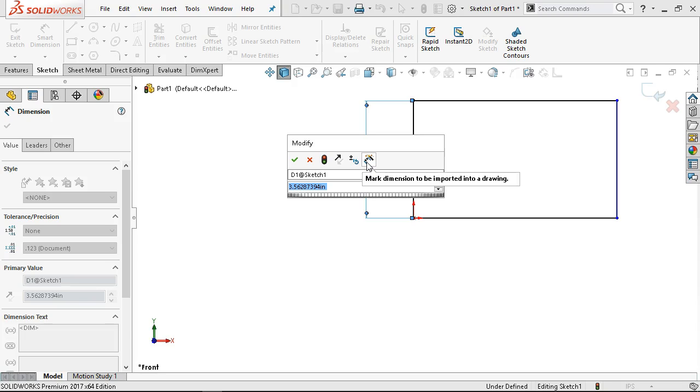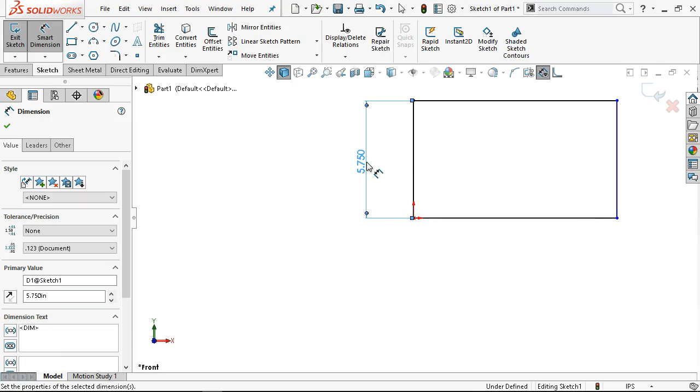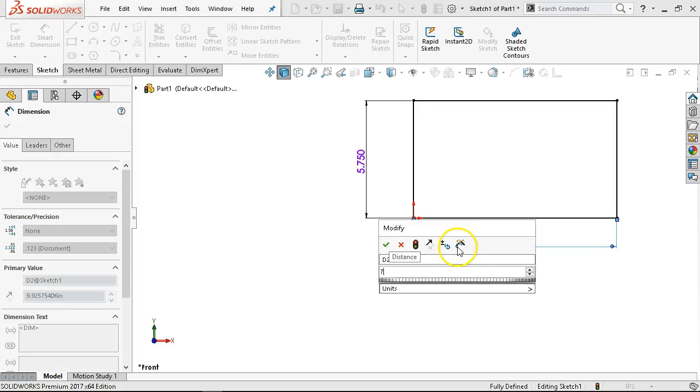So let's see, for our height, am I going to be looking at stack ups? Let's see, so to the center of the hole, 4.5 with a 1 1/4 radius. So that puts us at 5.75. If I find out that's not the case, then I'll have to make the adjustment. 7.5 on the overall.